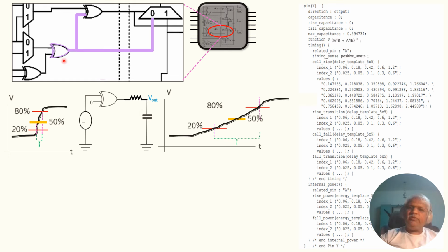There is another possibility: if that is not the optimal solution, the tool thinks, let me keep this drive strength as it is, and by combining it, maybe put some additional buffers here, and then we will be able to drive this net properly.